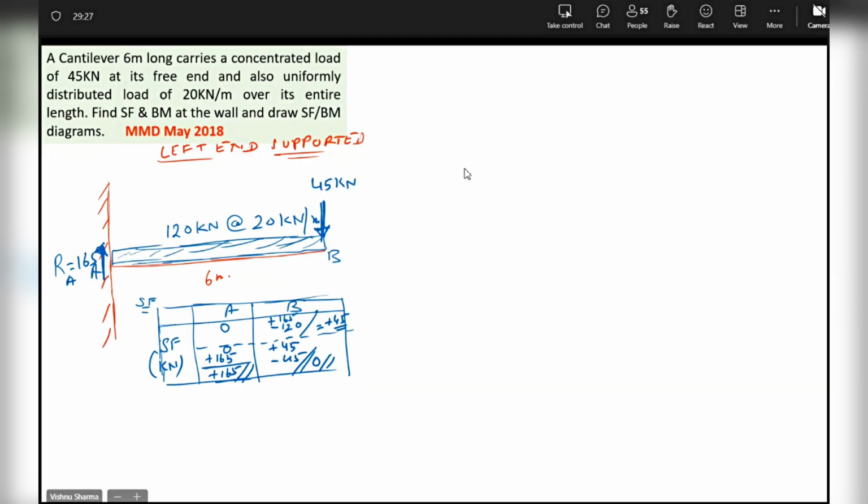What I am saying is, for shearing force, what do you look at? What is the change from A to B? So from right of A to left of B, what is the change? Yes, sir, only the UDL weight. So that is what we have brought, no, beta? Correct? Okay. And then from left of B to right of B, the 45 concentrated load comes and it becomes 0. Yes or no? Am I right?